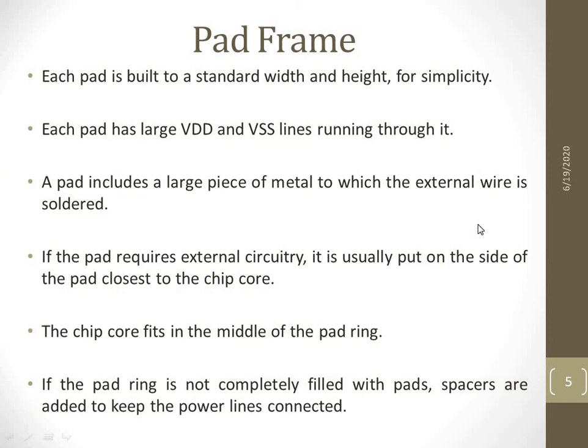If the pad ring is not completely filled with pads, spacers are added to keep the power lines connected. So spacing between the pads has to be kept if it is not completely filled, so that in between we can pass the power lines.